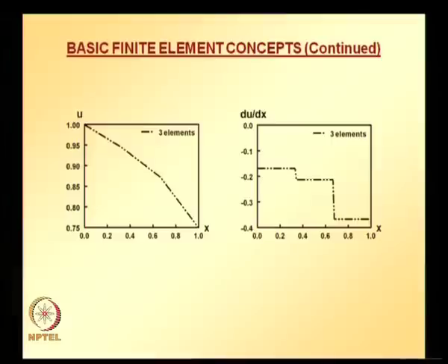The concept of assembly of element equations to form global equations gives the finite element method a great deal of versatility. The assembly process is very mechanical: once you get the element equation, substituting the nodal coordinates and length of the element, all these things are mechanical, and this is ideally suited for computers. These concepts will prove even more valuable when dealing with more complex 2 and 3 dimensional problems.